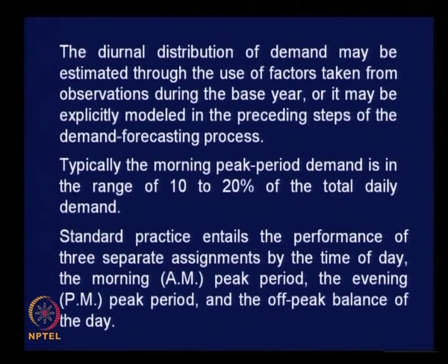As traffic engineers, you might know that you cannot have a single signal cycle for the whole of the day to manage traffic at intersections, even though in our country in many cases they just fix only one cycle time and manage to regulate the traffic. You should have different cycle times and different phase splits, one for morning peak, one for evening peak, and one for non peak hours. If necessary, you can go in for more cycles also, and traffic signals should be really dynamic, because truly dynamic traffic signals are vehicle actuated traffic signals.